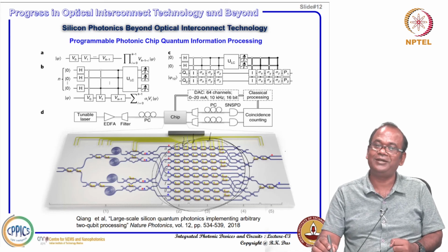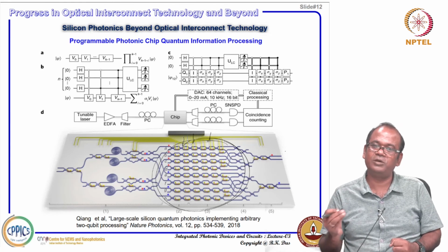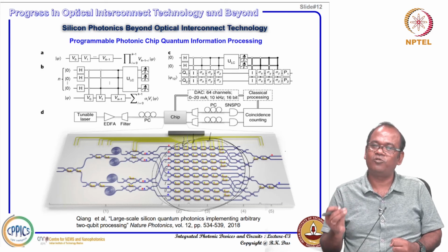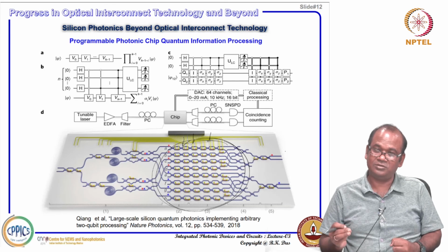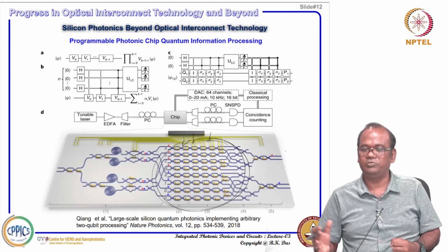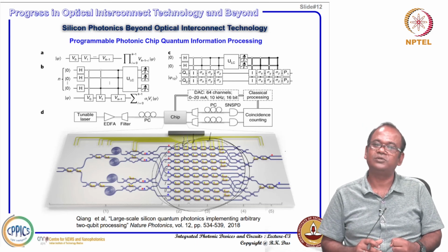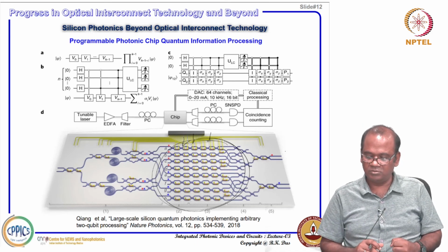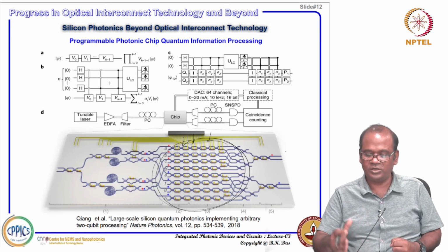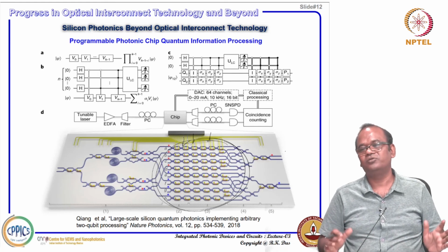Okay. So, huge things are coming, though once it is processed, the quantum nature of the photon you need to detect with a very high performance photo detector. So far single photon level sensing, on chip sensing, is very difficult. People are using the so-called superconducting nanowire single photon detector, SNSPD, and that has to be done at cryogenic temperature. So, detection normally is being done nowadays off chip. Sometimes people have made some progress on on-chip integration, but performance is lower. In this example they have used the photo detector outside, and that thing is also coming in.